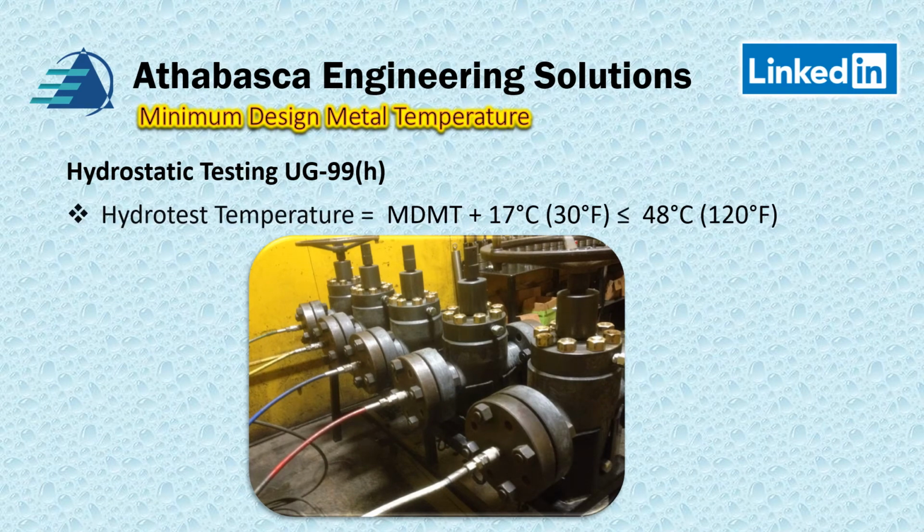So if I wrote it in terms of a formula, your hydrotest temperature per UG99H must be the calculated MDMT, okay, and you have to do the entire vessel, all the components, and get the warmest one, right? And then you put a margin, and that margin must be 17 degrees centigrade. And they're saying that temperature doesn't need to exceed 48 degrees centigrade. Now, that's by code. Some clients have very specific requirements, but this is the code.